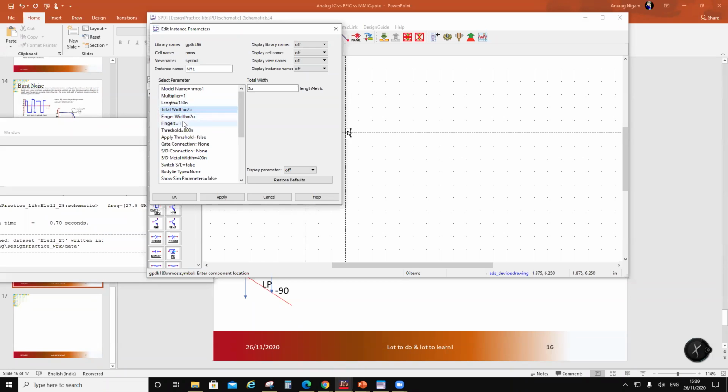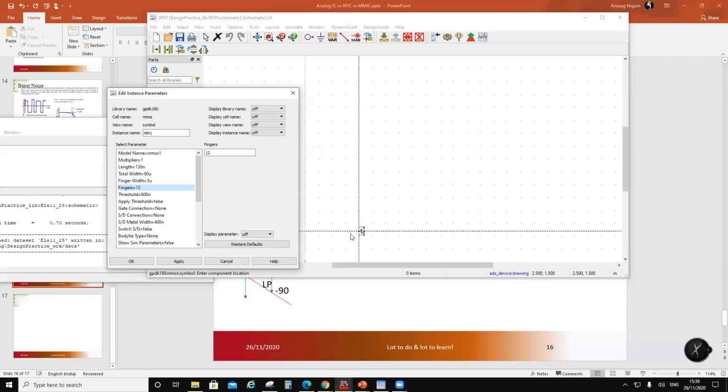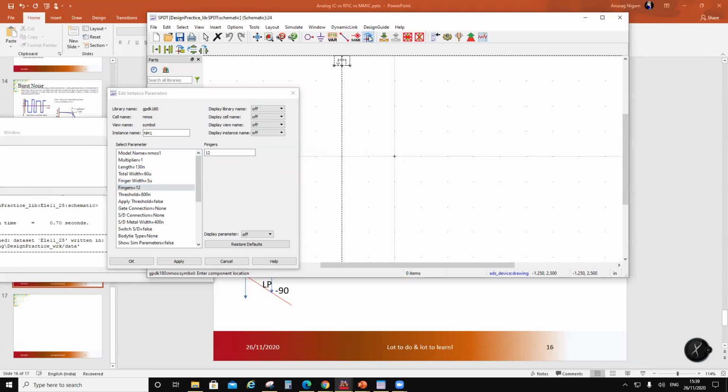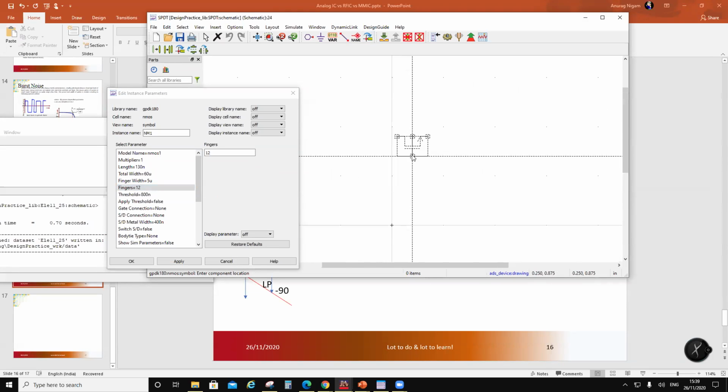So we are going to need a series pass element. I need some big transistor as a series pass element. So this is 60 micron. Now, a little note about these SPDT switches. These are like absorptive switches, so even if the path is off, you are still going to see a 50 ohm, right? So let's mirror it.